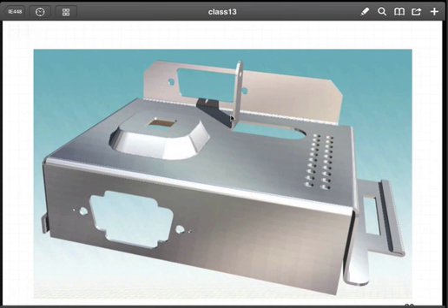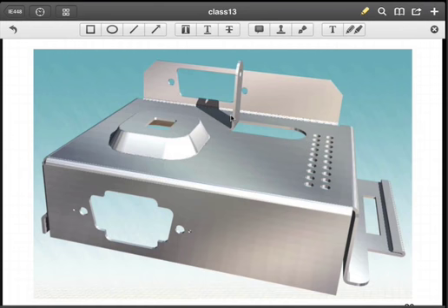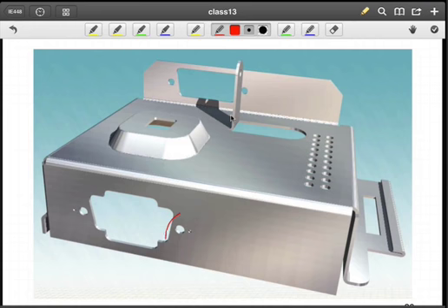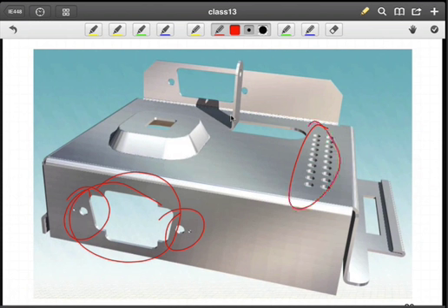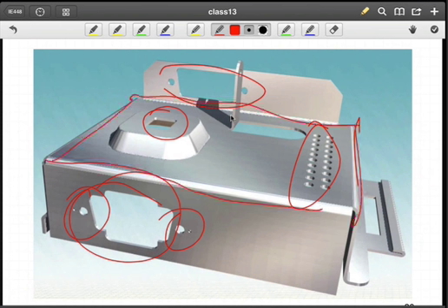Here we've got a forming operation where I am, again, creating certain product characteristics through a set of punch operations in terms of stamping. So you can see features in the side here, features in the top, that were created through stamping operations, and we're also doing some bending operations to create our edges here. So if we have a defect in this case, can we rework this product? Again, it depends upon the nature of the defect.